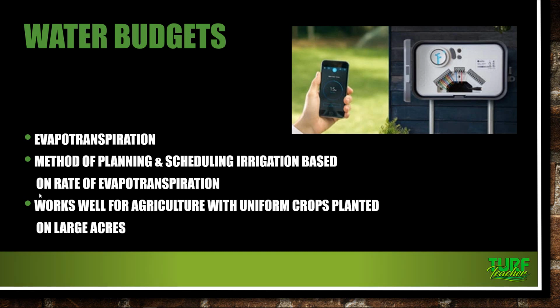The problem that they give us in this worksheet is a landscape area of 12,290 square feet, and we multiply it by the ETo value, or evapotranspiration value. It came up to be 6.43 at the location that this was done. Let me get my calculator opened.